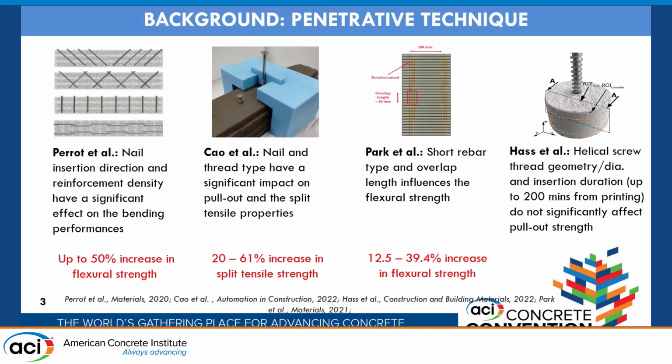So the penetrative technique is one of the most attractive reinforcement integration techniques because it has the potential for full automation, and also you can provide some kind of interlayer reinforcement to your 3D printed element. Several studies have shown how using short discrete reinforcement such as nails, staples, and screws can significantly improve the mechanical properties of your 3D printed elements.